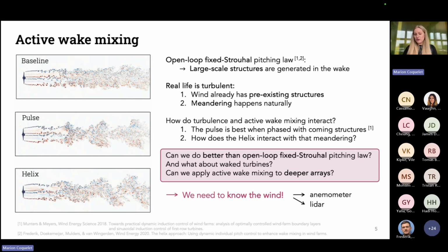Now, if you have an in-between, you don't want to add an instrument onto your turbine, but you do have blade load sensors, then you can consider that your blades operate as sensors because you measure the forces that are exerted on them. So you have a reflection of the wind speed, and you can, out of those blade loads, estimate the wind. And this is a trend that we've also seen emerging in the community, to really use rotors as sensors of the flow.